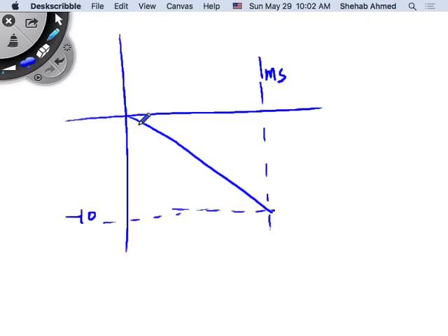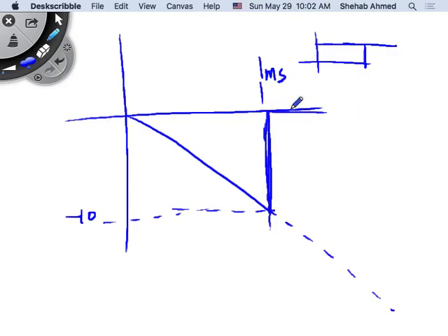And now, if I kept the square wave at the input, what's going to happen to this? It will just continue. Since I have a square wave ending at 1 millisecond, it stopped here, and the output looks like this. Now, if I add the feedback resistor, what's going to happen to the case with a very large feedback resistor at 10 milliseconds? Assuming this pulse was kept for 10 milliseconds.